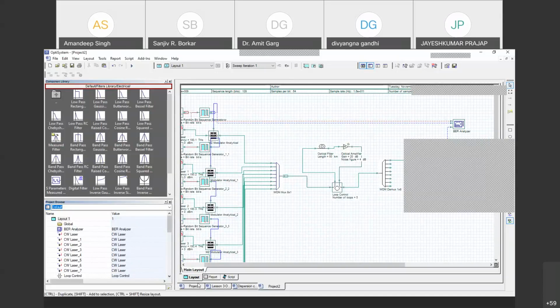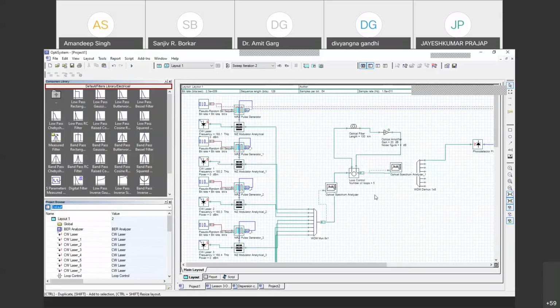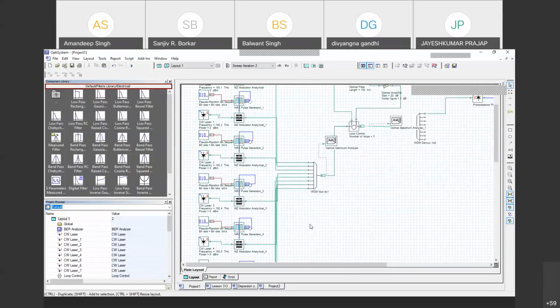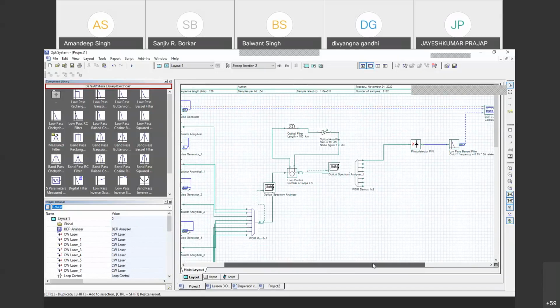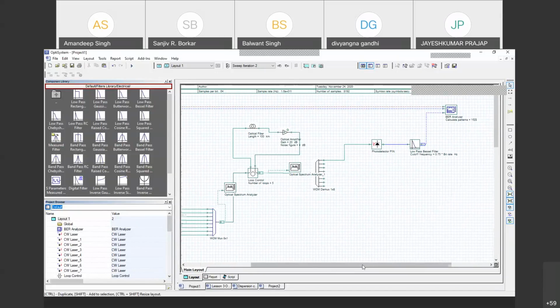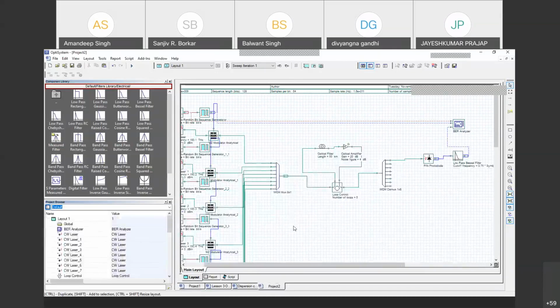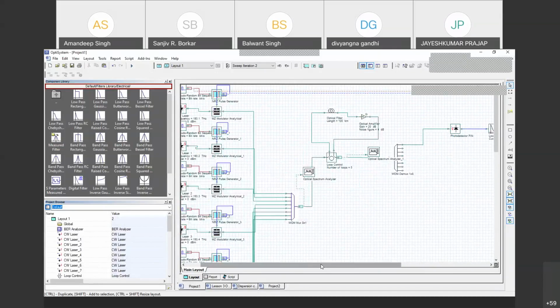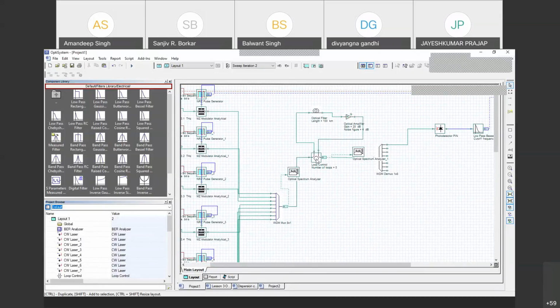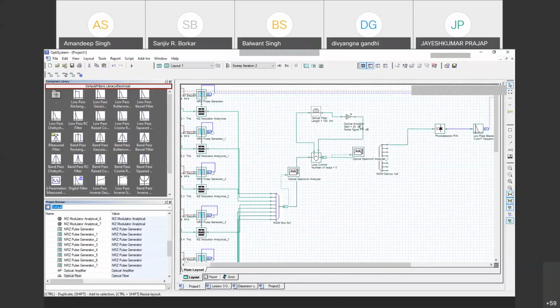Okay, coming back to this project. This is one of the projects, a similar one that I simulated earlier. In a similar way, whatever I have designed here, this is the same one. I am using the number of loops as 5 and optical length of 100 meters with an optical amplifier of 20 dB, the same concept.